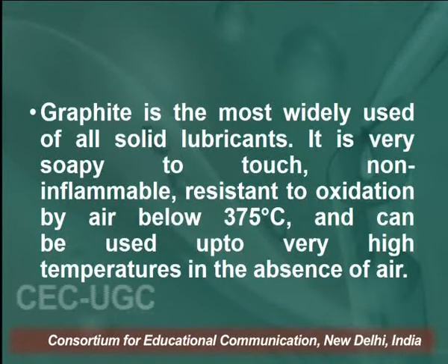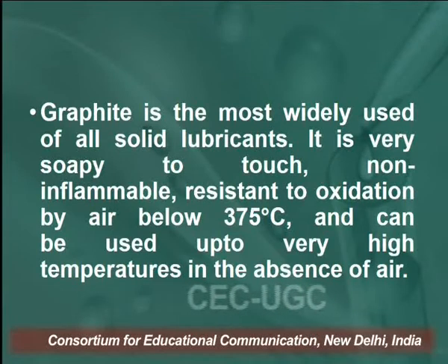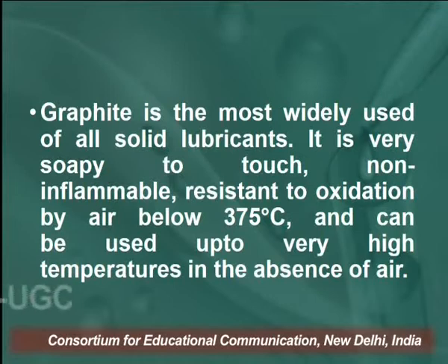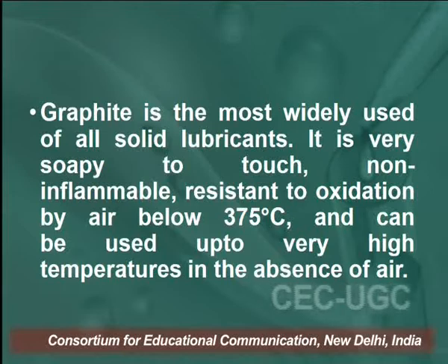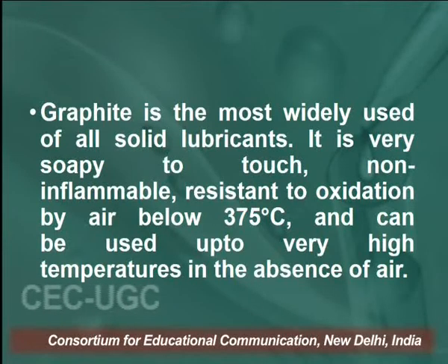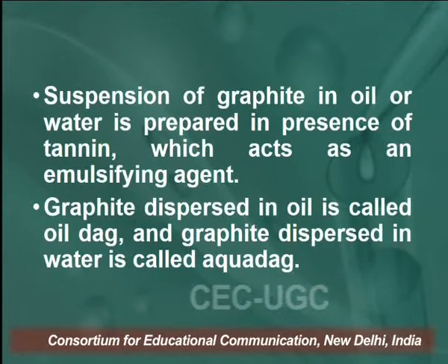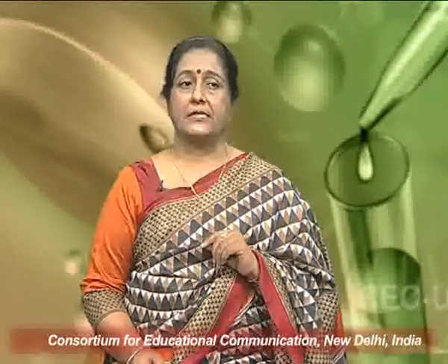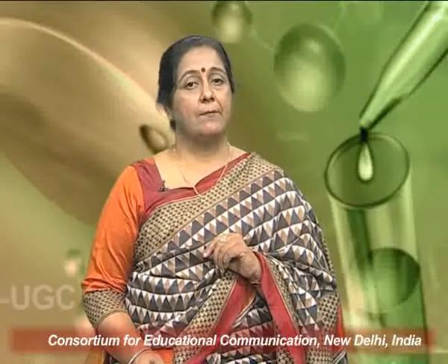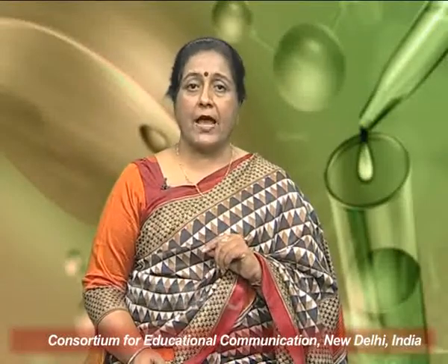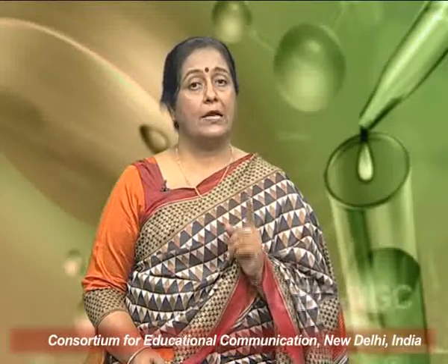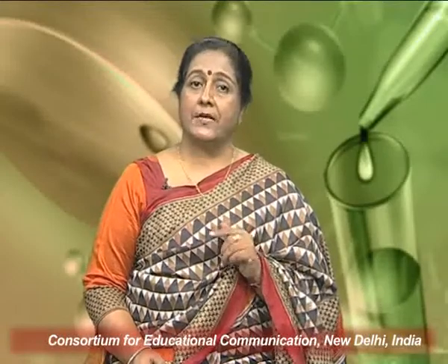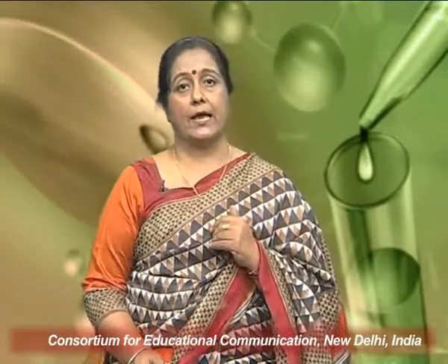Graphite is the most widely used of all solid lubricants. It is very soapy to touch, non-inflammable, resistant to oxidation by air below 375 degrees centigrade and can be used up to very high temperatures in the absence of air. Suspension of graphite in oil or water is prepared in presence of tannin, which acts as an emulsifying agent. Graphite dispersed in oil is called oil dag, and graphite dispersed in water is called aqua dag.